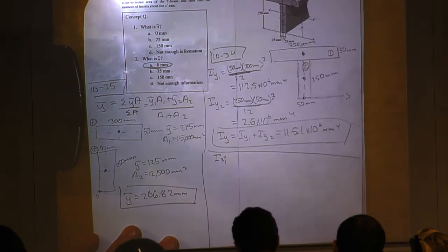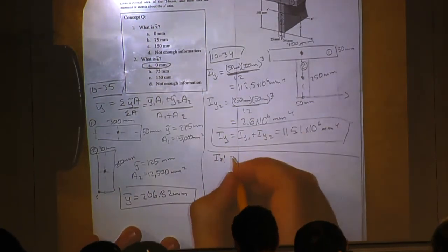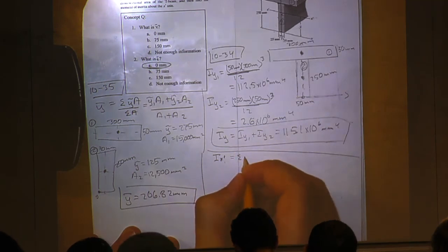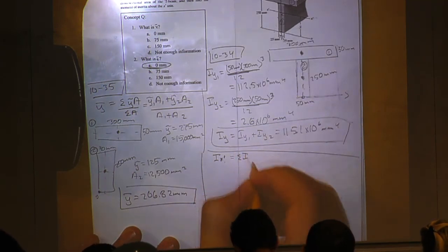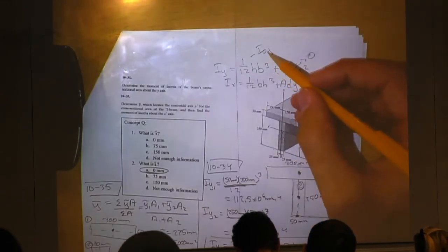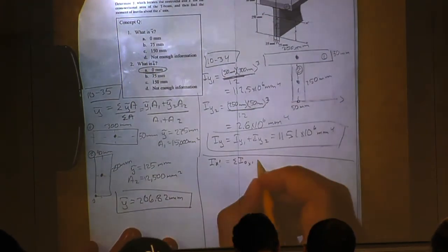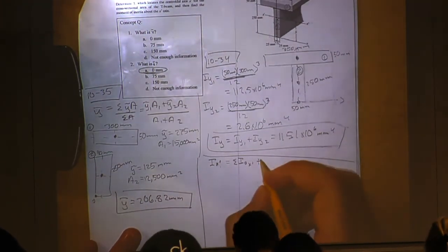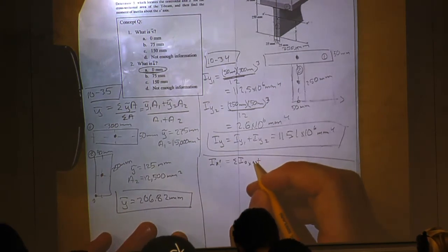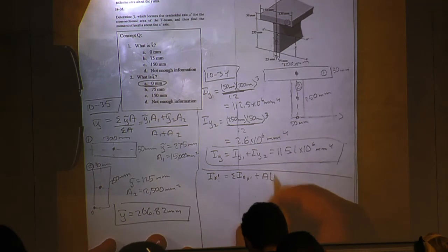Is equal to, right, the sum of my I naught x primes, right, because I said it earlier, this is our I naught part of our equation. And then here we are going to have some distance from our centroid to the centroids of our other shapes. So we're going to need to include that differential y distance.